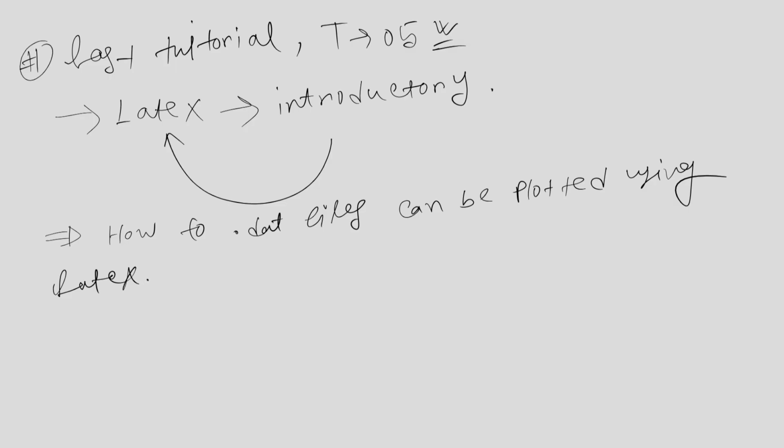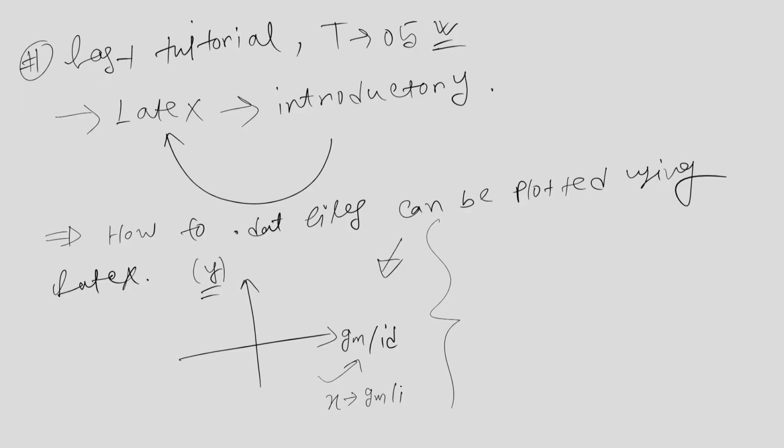Although Cadence does not directly provide you plots with, for example, GM over ID on the x-axis and your parameter on the y-axis, if you need such plots for circuit design purposes, you need to generate them.